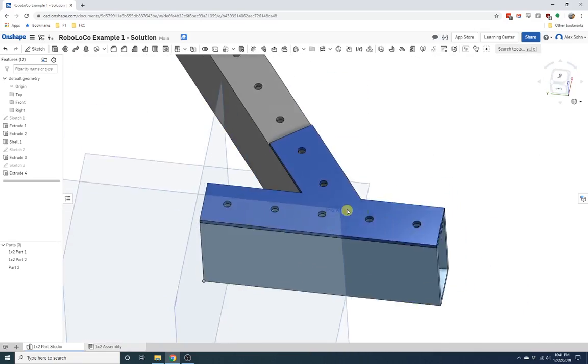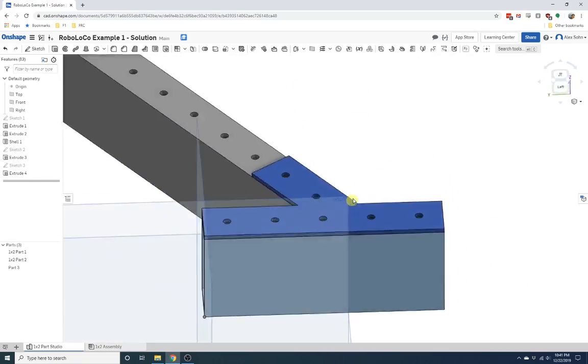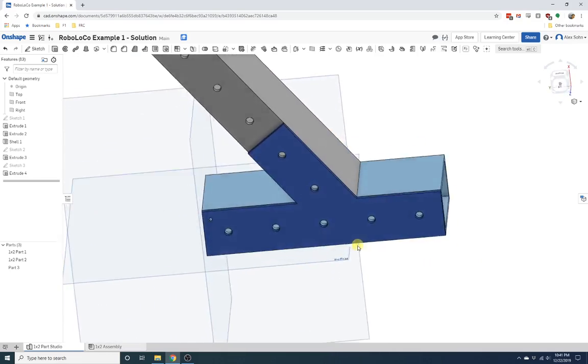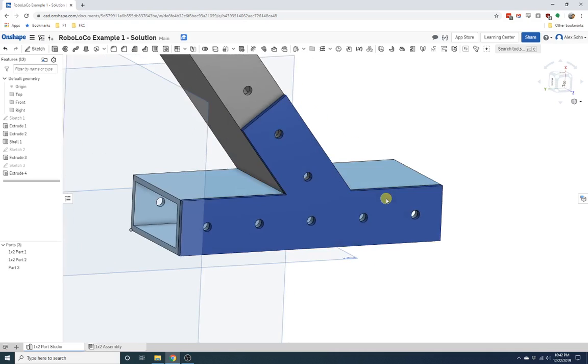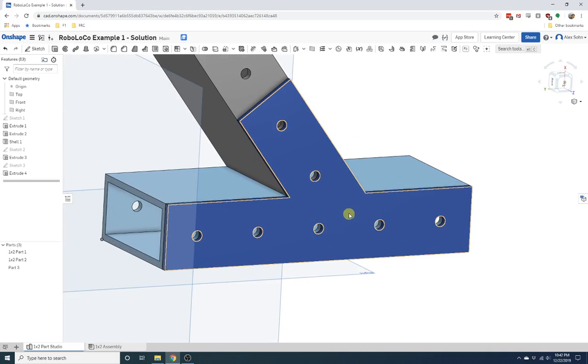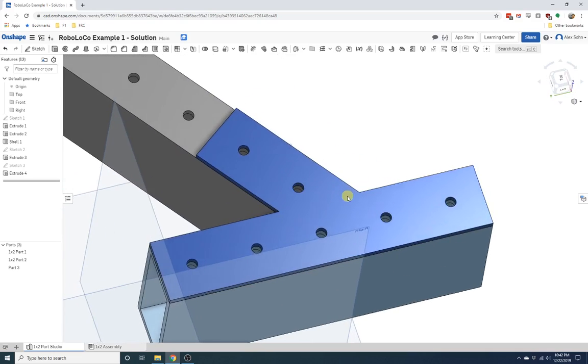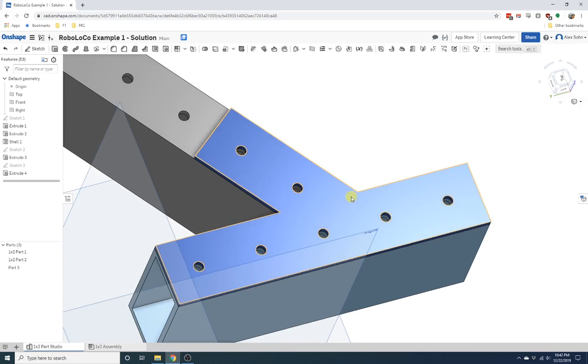So we're almost ready to get there. So one thing to note, you can have a bracket like this if you wanted. It won't be very manufacturable. Whenever you manufacture something, note that whatever the cutter is that you're using, usually it is a circle, whether it is a water jet or a wire EDM or a router like we would use.